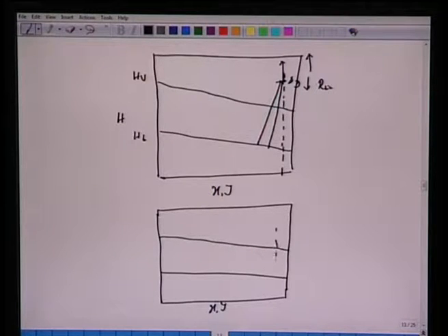We know the last coordinate, which is 0.92 given to us. So all we do from here, this is your Y1, first tie line, first stage, we have the X1. So the top plate, vapor leaving and the liquid leaving, they are in equilibrium.